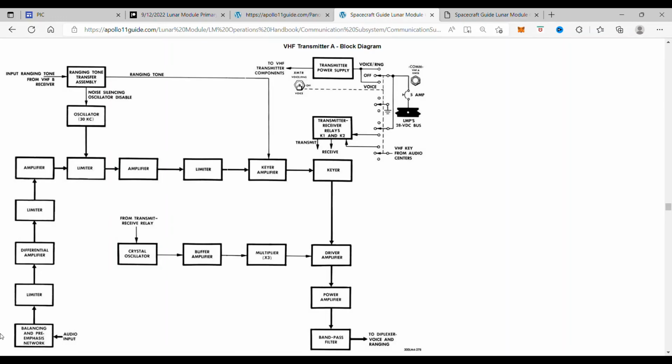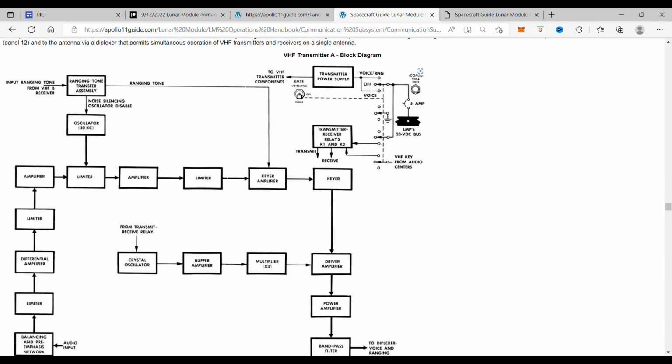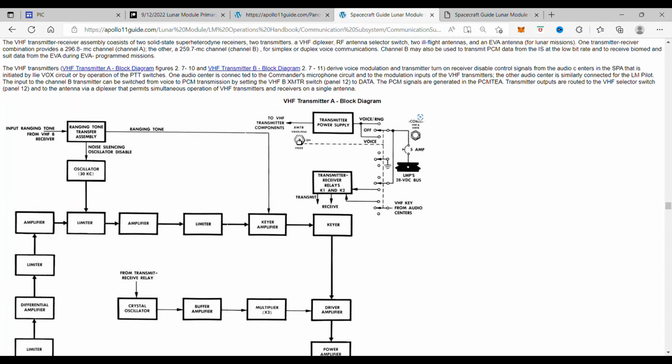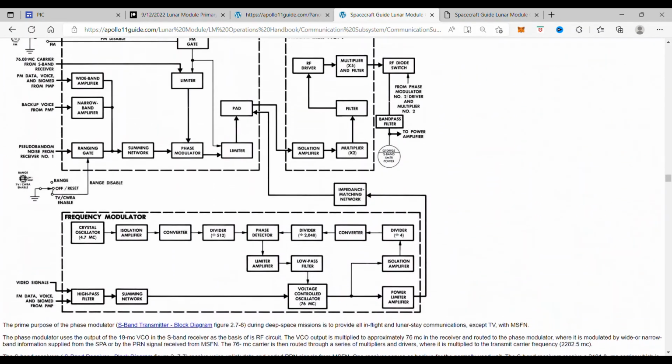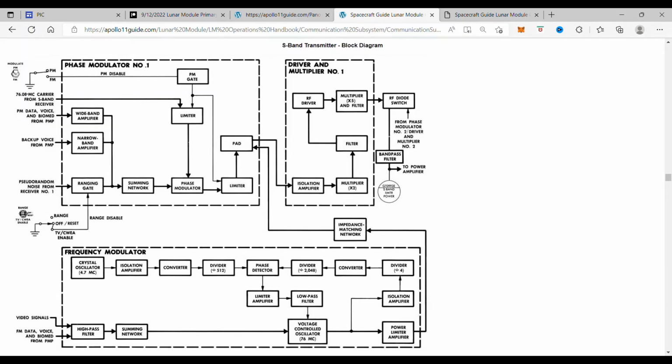Communications with the Command Service Module may be accomplished by using the Manned Space Flight Network as a relay. Lunar Module, Manned Space Flight Network S-band capabilities are the same as in-flight capabilities, except that, in addition, TV may be transmitted from the lunar surface in an FM mode.